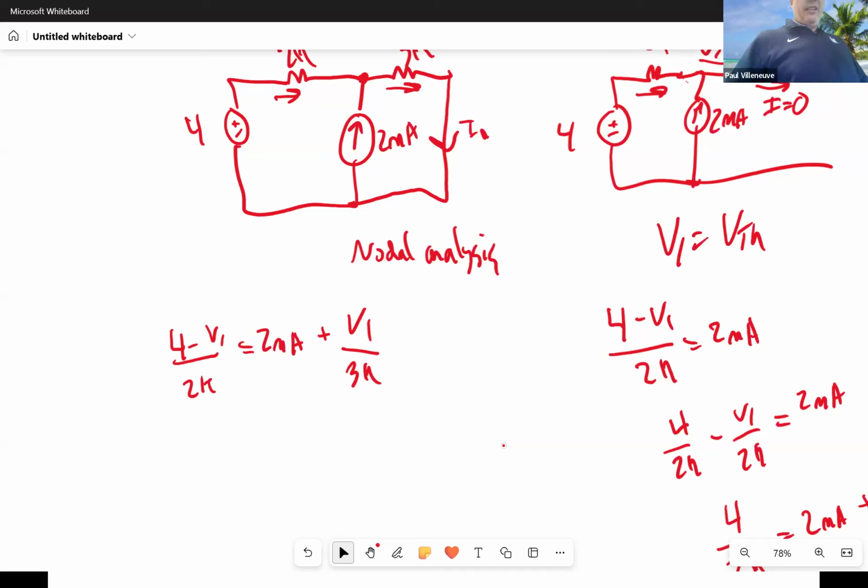So let's see. So 4 divided by 2K is 2 milli, minus V1 over 2K, equals 2 milli plus V1 over 3K. I'll bring my V1s to the same side.